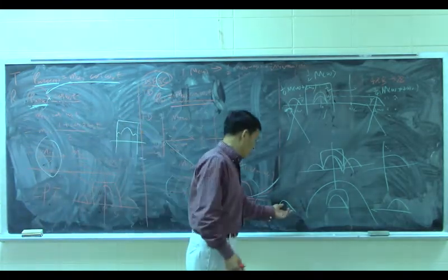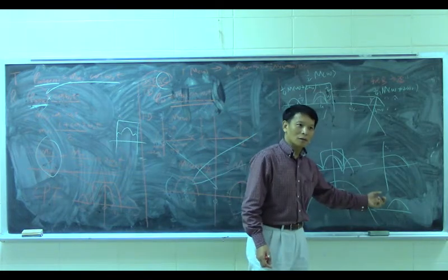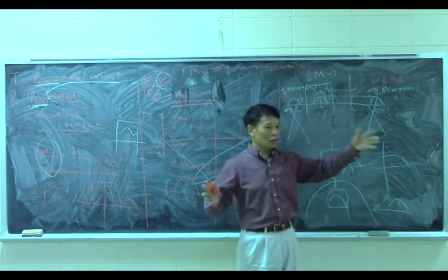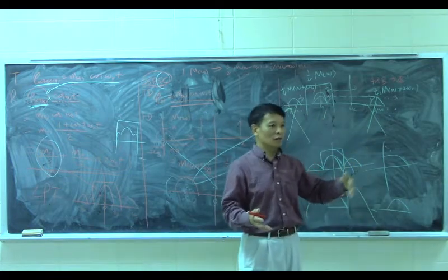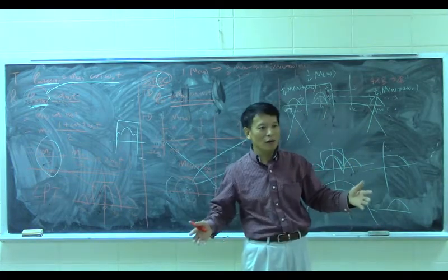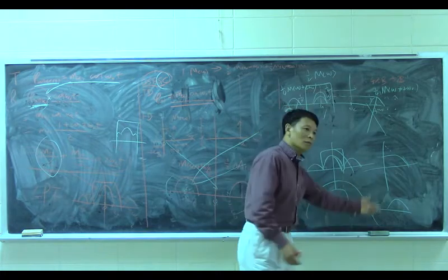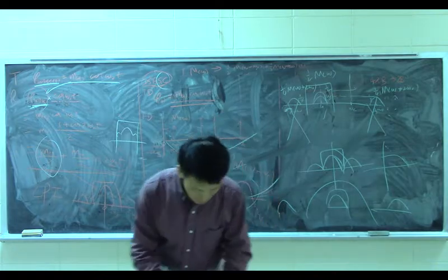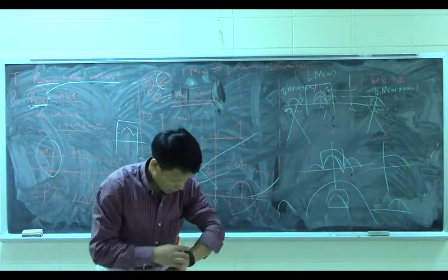I was saying, so the low pass blocks out all the other stuff. Yes, the low pass will cut off the high frequencies. So you want to choose this omega C a little bit larger usually, for example, like 20 times or 100 times larger than this one. So you can make this filter design much easier. Okay, any questions?